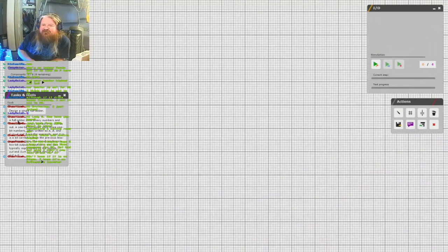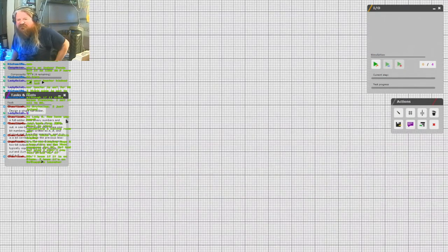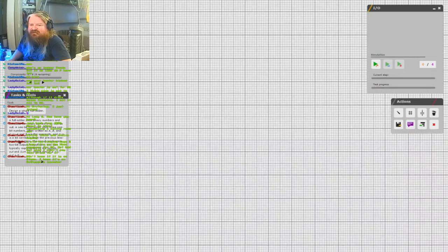Design a single full adder. A full adder adds binary numbers and accounts for values carried in as well as out, and a 1-bit full adder adds 3 1-bit numbers, often written as A, B, and C in. A and B are the operands, and C in is the bit carried in from the previous, less significant stage.